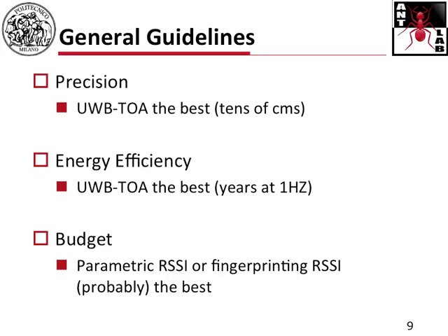We have already mentioned yesterday that systems based on time of arrival may have some problems where you have reflections of the signal, so where you don't have line of sight between transmitter and receiver, because in that case, if you have reflection, your synchronization may somehow get lost.